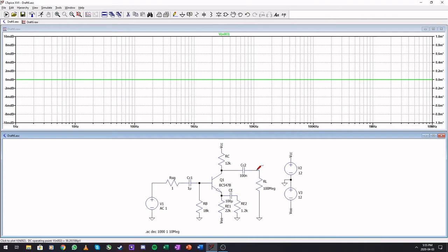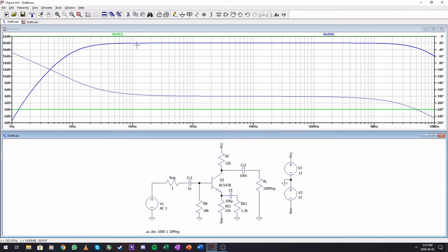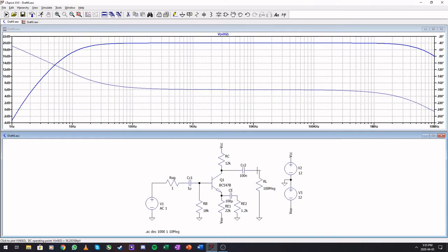If we go to this end of the amplifier, you'll see that we have a lower cutoff and a much higher cutoff that we can't see because this is too low. Double click to take the green away. And here in the middle we have a passband gain. Our amplifier is designed to give a gain of 10, and that is 20 decibels.